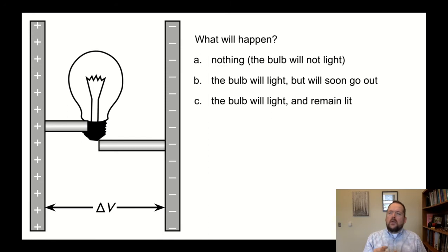But in that context, you actually can use a capacitor as a short-term storage device. In fact, many photographic flash units have capacitors built in so that when you open your shutter to take the picture, the flash flashes. A capacitor discharges through the light bulb, and then it is some period of time while that capacitor is recharging before you can flash the unit again.